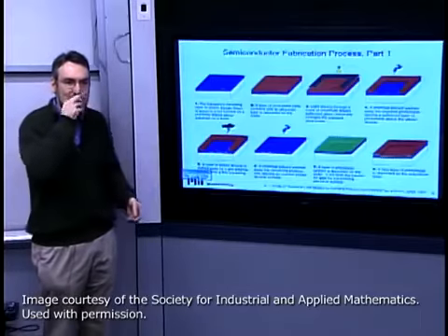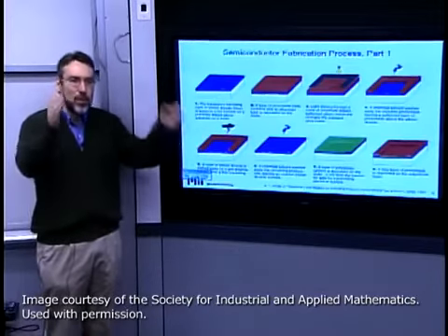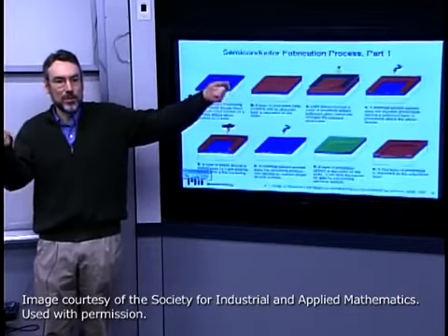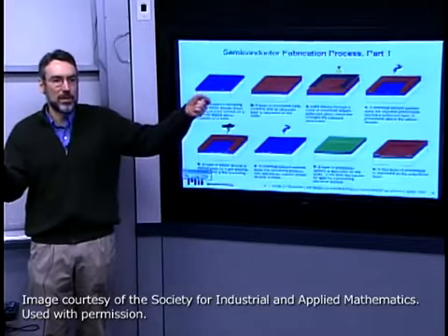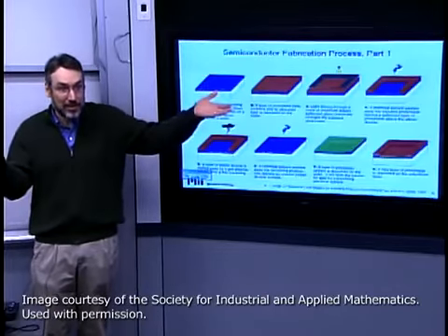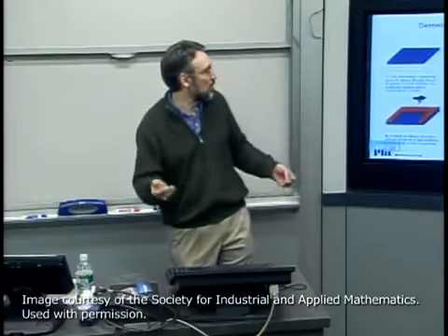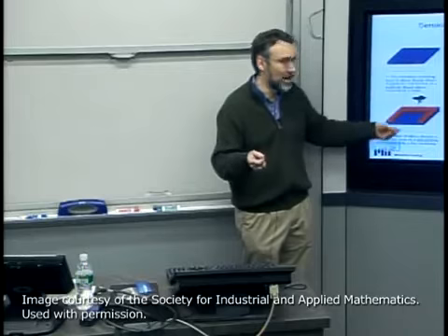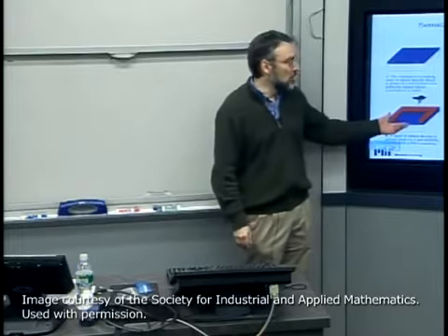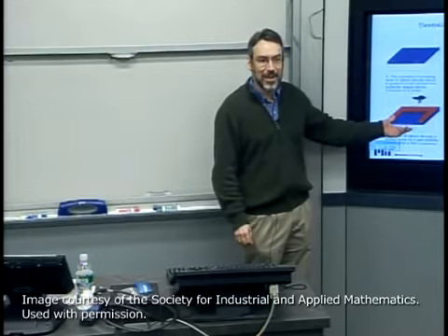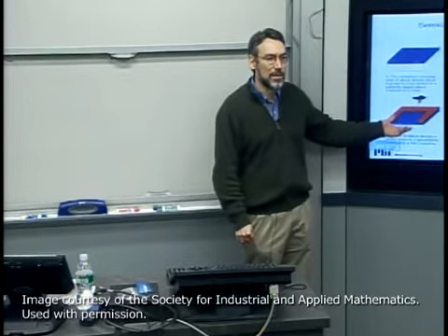By the time I get down to etching 4,900 angstroms everywhere, that little 1 out of 5,000 controllability or variability, which is not bad, that'd be great if I got whatever that percentage is, 0.05% or 0.02% or whatever. I mean, that's amazing, but it would magnify by the time I etch down, even if I could etch uniformly. There's just no way, most importantly, to be able to know when you're within 100 angstroms and be able to stop controllably at that level.